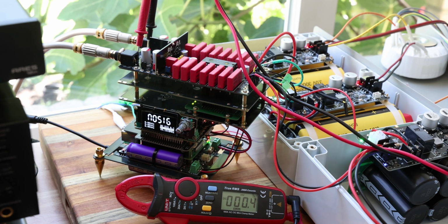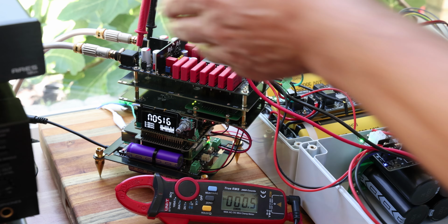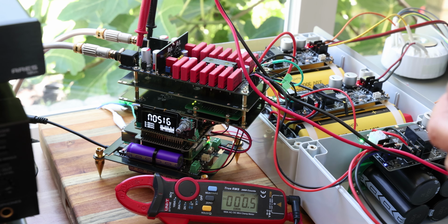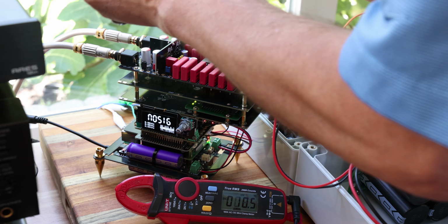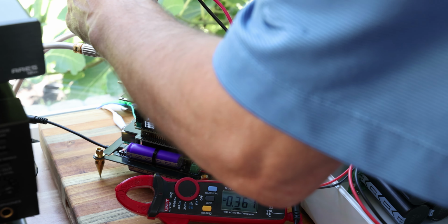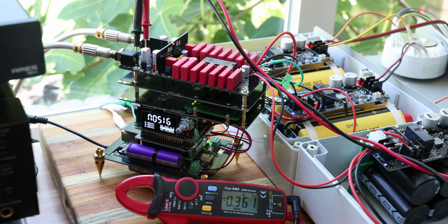Once it's running fine, just to make sure you didn't solder something wrong and suddenly you've got 15 volts here, also measure so you see exactly what's going on. So let's measure the other side out of curiosity. We're going to flip those around and just measure the other side to see how it measures. And it's measuring 0.36 volts. So let's adjust that.